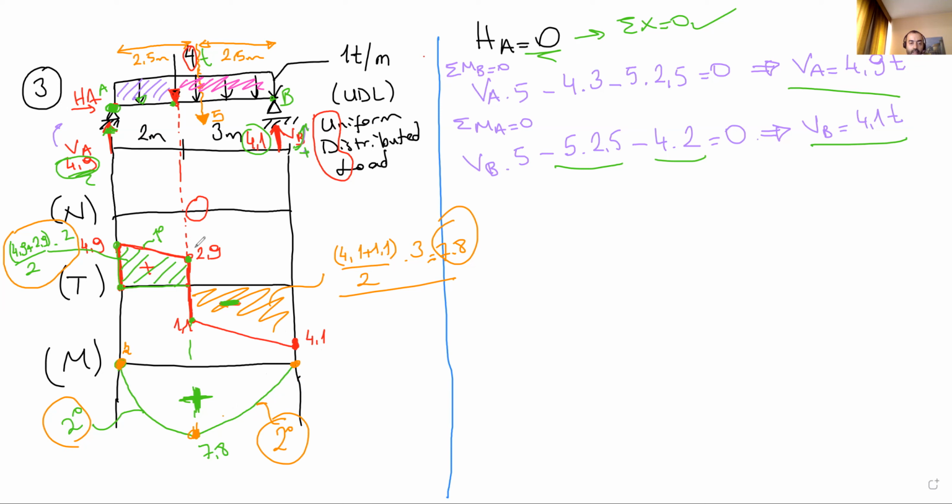By the way, here there was a rule, remember, for the shear force diagram. When the shear force diagram goes through 0, at this point there is the maximum moment value. As you can see, at this point we have the maximum moment value. This is the axial force, shear force and moment diagram of the simple beam under the given loading condition. Any questions so far?